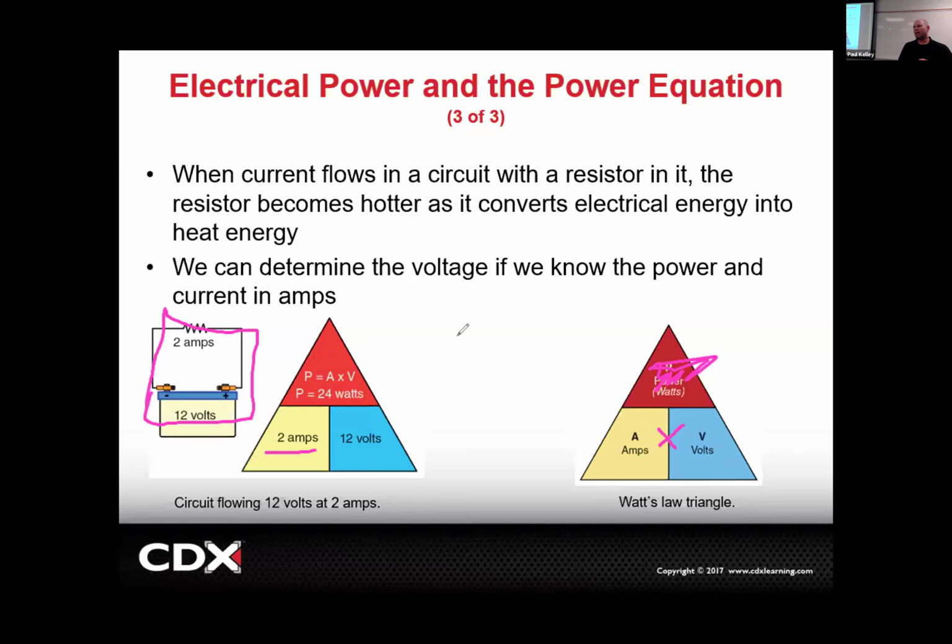They don't have wire for a 24 watt power system. They have wire that's a gauge size that tells you how many amps it can handle. So if you know how much power that particular item is going to consume, and you can determine the voltage, you can determine how many amps will be drawn through there, and you can size the wire correctly, right? That'd be more like what an electrical engineer would do.